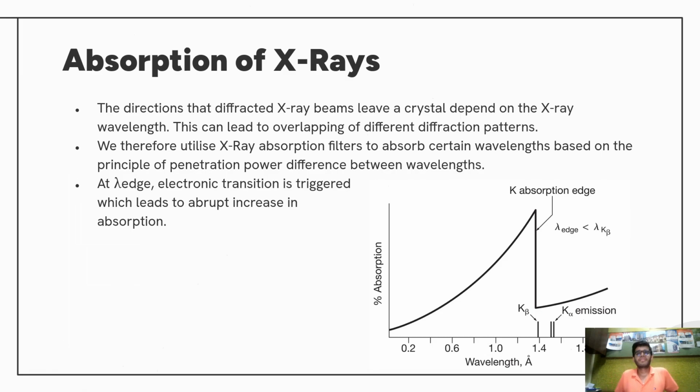And the way these absorption filters work is, first of all, the material is chosen such that, we know that as we increase the energy of X-rays, the absorptivity, the percentage absorbed, decreases, because high energy X-rays are not absorbed as much as the lower energy X-rays. So we have, for instance, as shown in this curve.